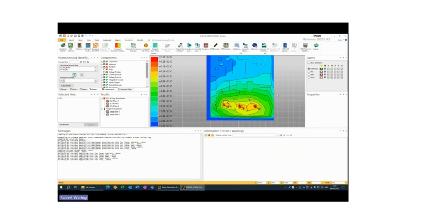There we go, and you end up with a temperature map, taking into account the flow that you've applied to it. So if you are at the point where you haven't designed your flow capabilities in your design yet, but you have an idea of what it might be, this way you don't have to worry about exporting all of your PCB and applying all of your maps. You can do it within the PCB simulation solver itself.